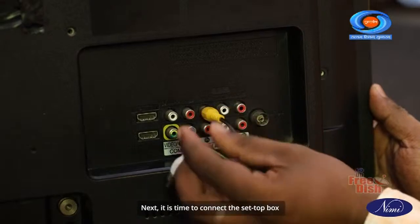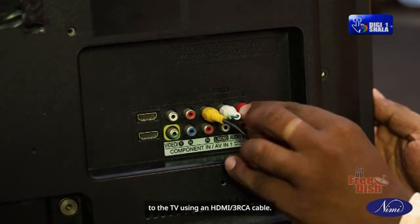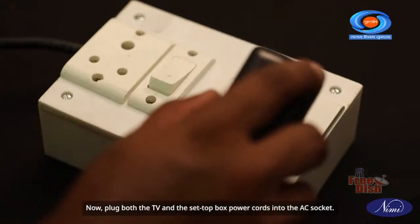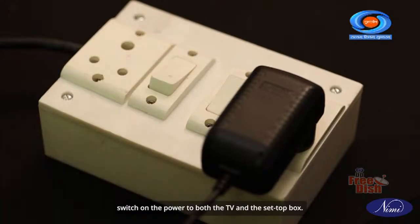Next, it is time to connect the set-top box to the TV using an HDMI or 3RCA cable. Now plug both the TV and the set-top box power cords into the AC socket. Ensure the cords are securely inserted and there are no exposed wires. Once the cords are connected, switch on the power to both the TV and the set-top box.